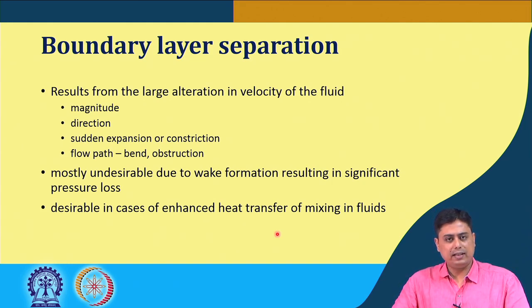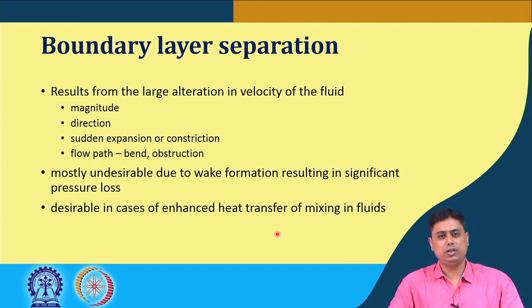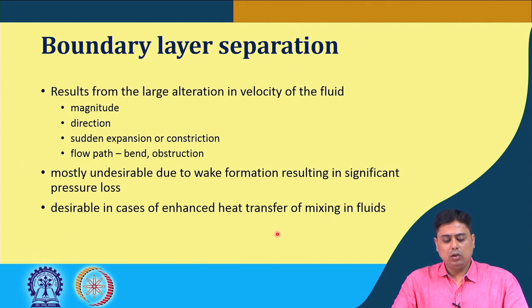So, boundary layer separation is mostly undesirable due to the wake formation that results in significant pressure loss, but it is sometimes desirable in cases where we require enhanced mass transfer or mixing of fluid. In those cases this kind of wake formation or local turbulence is helpful, and helps us to have the enhanced conditions.